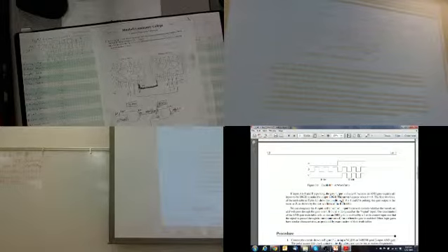What you have to do is get one of these cables. This is called a BNC cable, and then you have just some clips on the end. I want to connect it to CMOS TTL. TTL means transistor-transistor logic. It was the original standard. It's the 0 to 5 volt standard for logic. And then CMOS, they're different levels. That's what that is, 0 to 5.